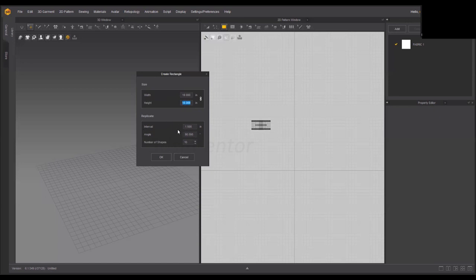And if I want to space all the squares with a spacing of 1.5 inch, what I have to do is just add 10 and 1.5. So this will become 11.5 inch. And now we have a nice spacing of 1.5 inch between each of these rectangles. So if I don't want any spacing, I can just write 10. So you can see we don't have any space between these rectangles.